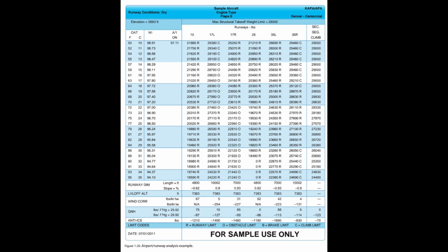Categories of departure procedures. There are two types of DPs: those developed to assist pilots in obstruction avoidance, known as ODPs, printed either textually or graphically, and those developed to communicate ATC clearances, SIDs, always printed graphically.